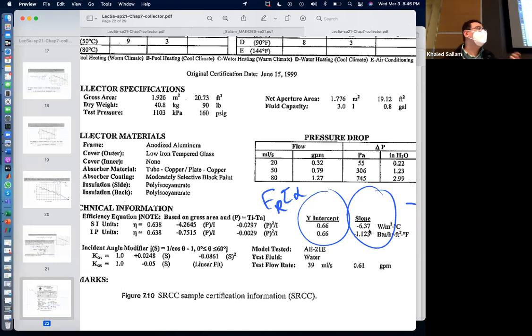We are actually going to design our water heater to do twice the load that the house needs, so we already have a factor of safety built in. If I'm like 5% off, don't worry about it. So they approximate the equation for simplicity, especially when the approximation is not that bad.